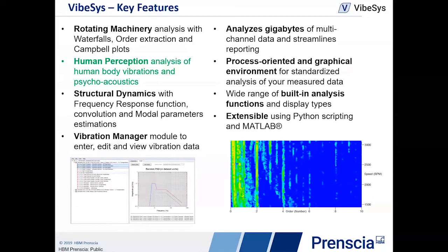The way you build analysis with VibeSys is the same as you do with Design Life or with Glyphox. It's a process and a graphical environment. Meaning there is no coding needed to use VibeSys. You don't need to write any single line of code. You can just connect the blocks and run your analysis just after having connected these blocks. At the same time, if you really need to code, or if you like coding, that's no problem. You can use Python, and you can use MATLAB to integrate your scripts or the things that are not built in the software. So thanks to this Python and MATLAB scripting availability, you can bring your own code into VibeSys and use what you have done in the past. You don't lose what you have done in the past. You can still reuse it within VibeSys.